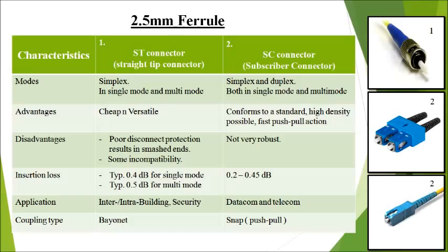Typically 0.4 decibel for single mode and typically 0.5 decibel for multi-mode for the insertion loss of ST connector. ST connector has been widely used in inter or intra-building application and also for security application. ST connector uses bayonet type of coupling.